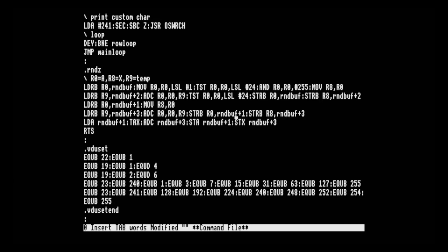So you notice the add instruction, there's two versions of that. Previously in the code I was using add with two Ds, and that doesn't involve carry. Here I do want to involve carry, so I have an instruction ADC, which means add with carry. So again, I can selectively choose whether I want to involve carry or not. I don't have to go around clearing the bit before or after doing the addition like I had to on the 6502.